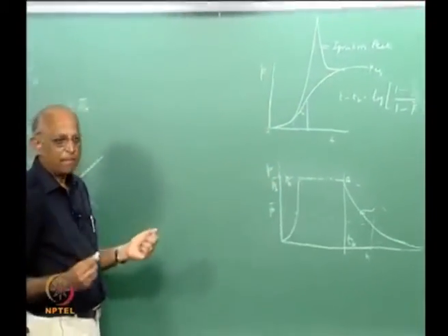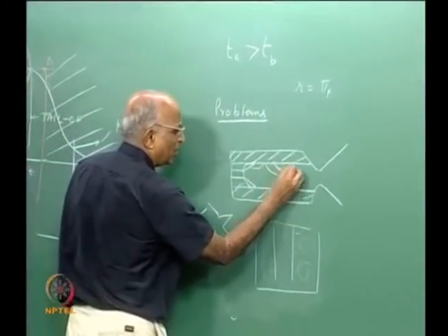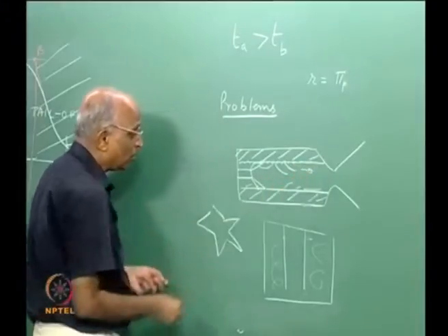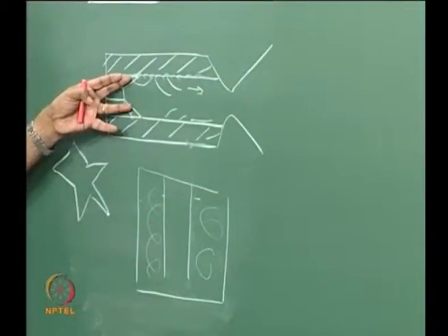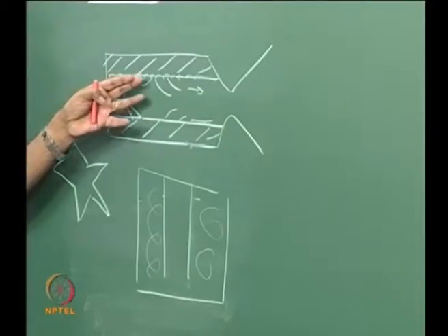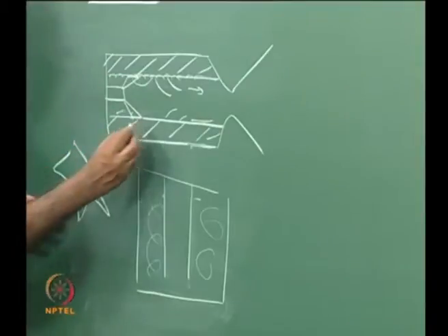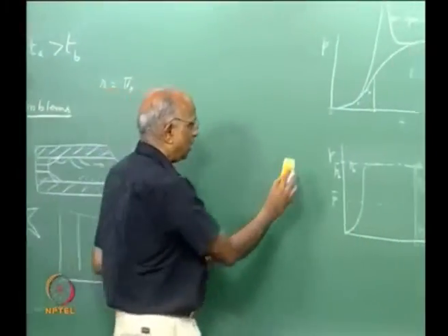This is one reason. The second reason could be that maybe I have high velocities, and it could lead to higher burning rates towards the end, and that is also possible. But to be able to prevent this, what is normally done is, we take something like an emery paper and remove the surface defects and ensure that the surface of the propellant is easily ignitable. Let us put it down.